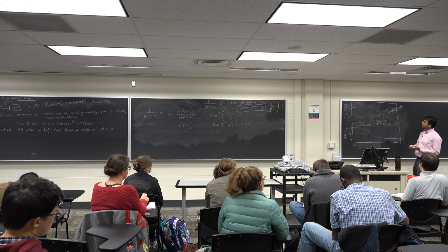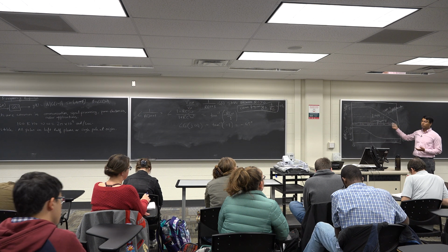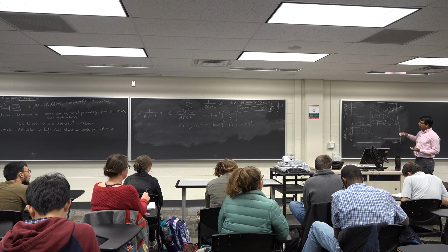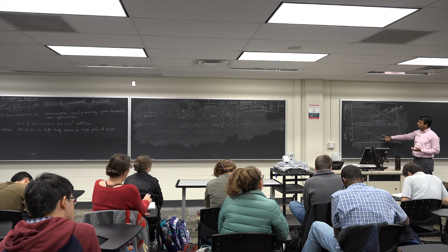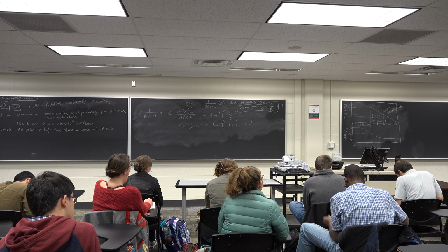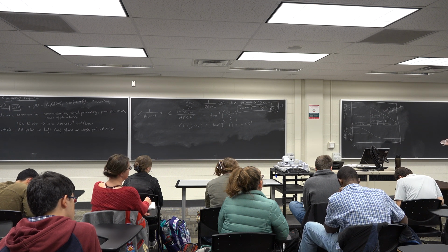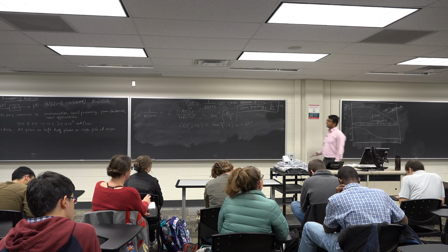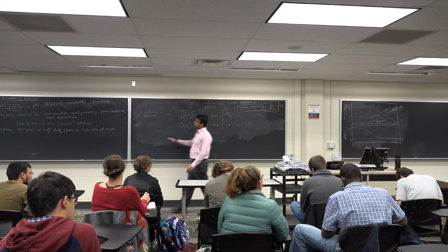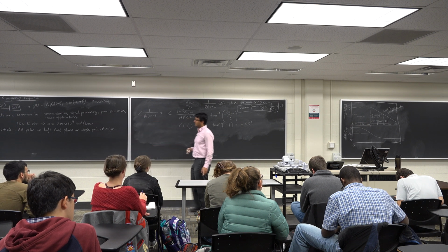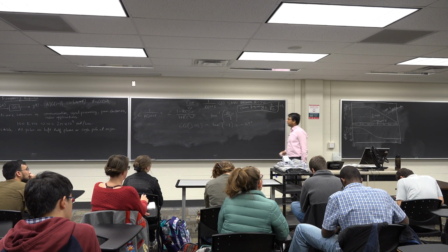It will give you information about how many zeros there are and where they are located. And then by looking at the phase plot, you can figure out whether the zeros are in the left half plane or the right half plane. Of course, our implicit assumption is that the system is stable, which means all the poles are in the left half plane, or you could have a single pole at the origin which acts as an integrator for the system.